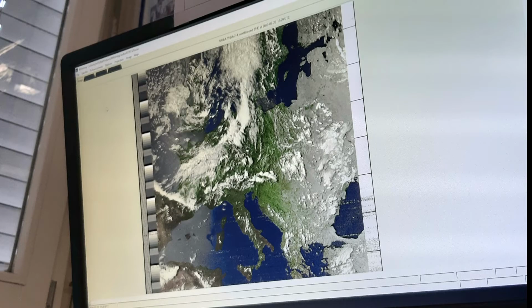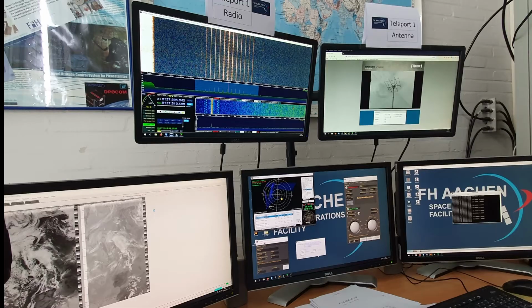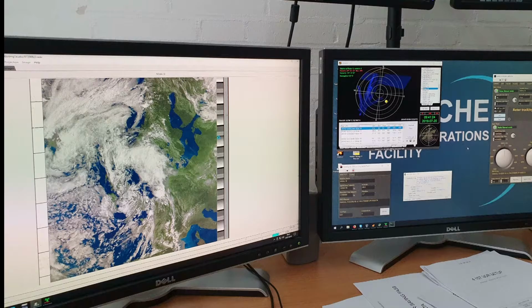This image comes from a NOAA-19 satellite, which is an American weather satellite. The signal has been recorded at a maximum elevation of 60 degrees. The next two images have been recorded at a much lower elevation, all by the students of this summer showcase. The results are still very good. This is due to a correct manipulation and by the high antenna gain of a whopping 21 dBi.